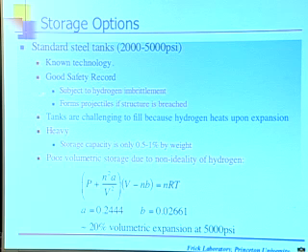Some have said that metal tanks are subject to hydrogen embrittlement, and this would be an issue. I'm not sure this is really an issue, in that in the lab we've been using hydrogen tanks for a long time, and we don't have them failing because of hydrogen embrittlement. But certainly some inspection routine would be needed. So there's a little something going on there, but I'm not sure that's a real problem.